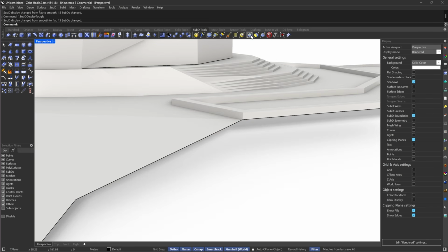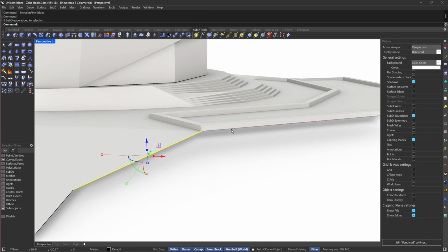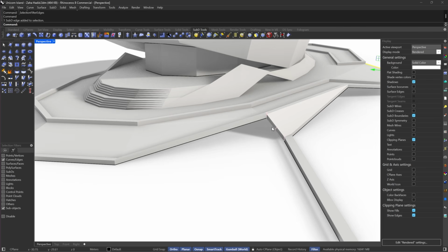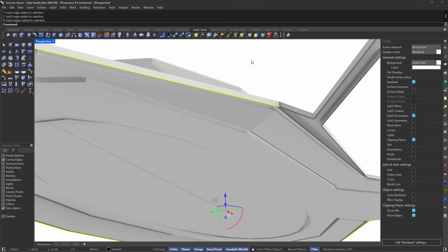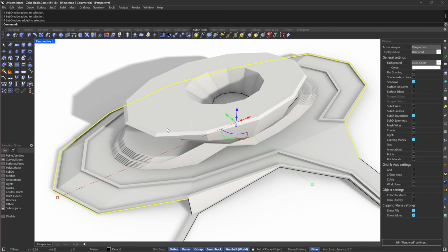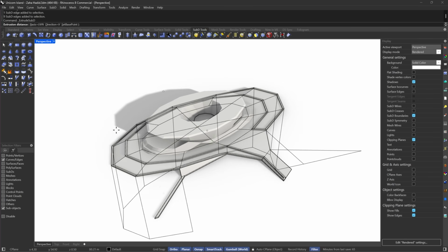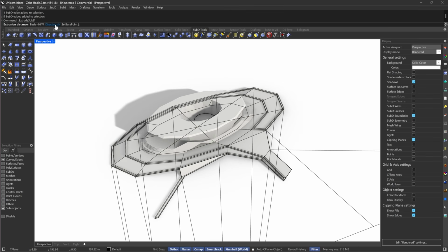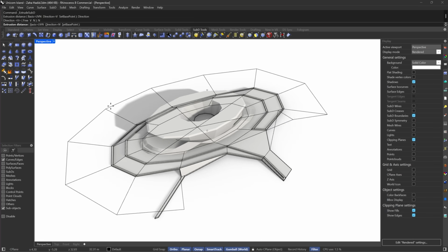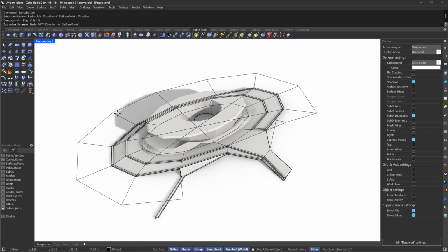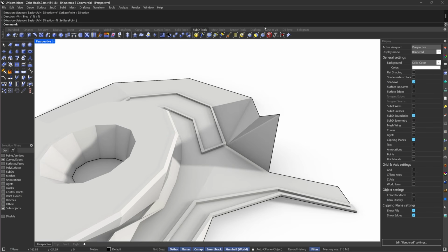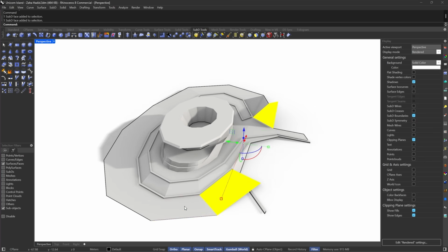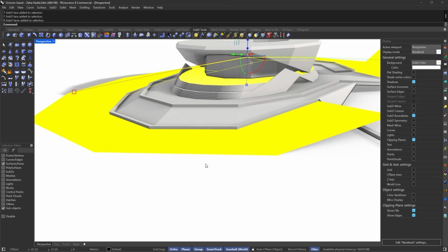So right now I might just select maybe from here to here. Probably I like all of these edges, which are exterior edges at this point, and then I'm going to extrude, and right now it's extruding in the V direction. I want it to extrude in the N direction, which is the normal direction, and right now it's doing something like this, which is good, but I want to fix all of that, so I'm going to select all of this and probably Gumball relocate.